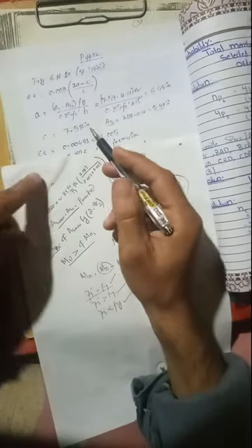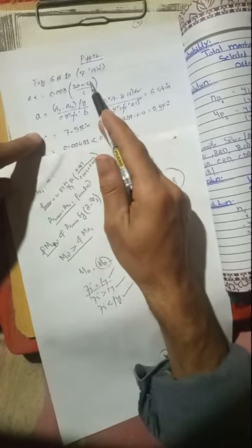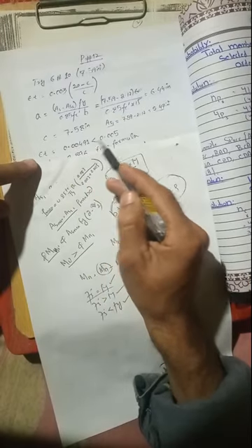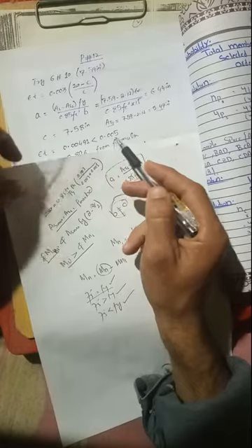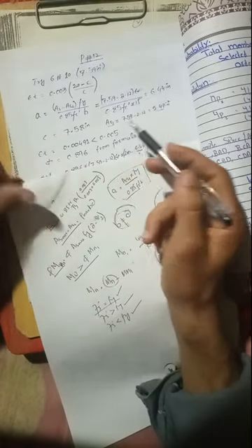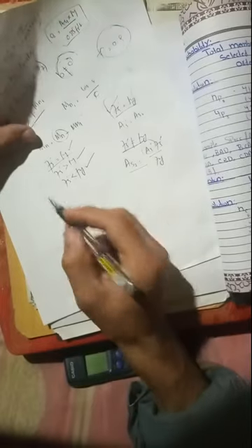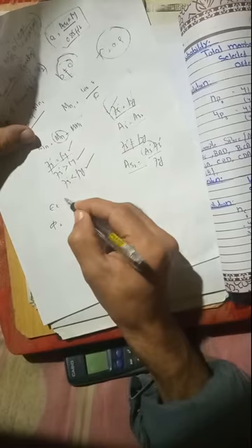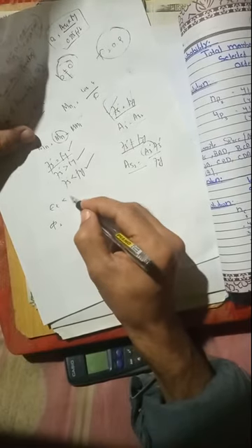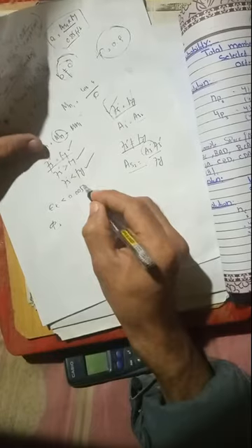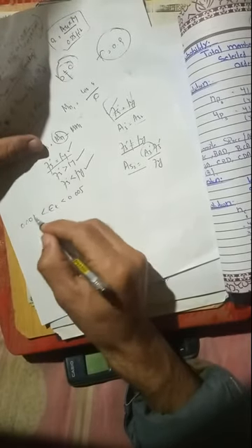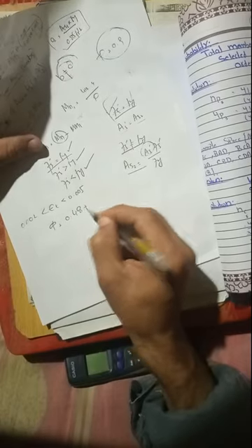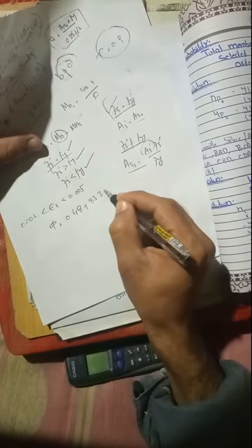Now, once you got the c value, just plug the c value right here. You find the epsilon t value, which is 0.00491, which is less than 0.005. So from the formula, which I already explained in lecture number 3, when your epsilon t value is less than 0.005 but greater than 0.002, you have to calculate the phi value from the relationship 48 plus 83.3 into epsilon t.